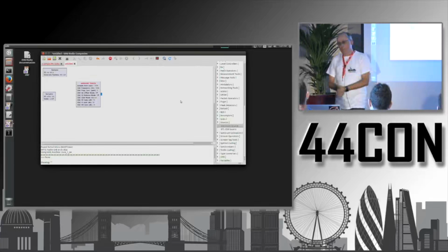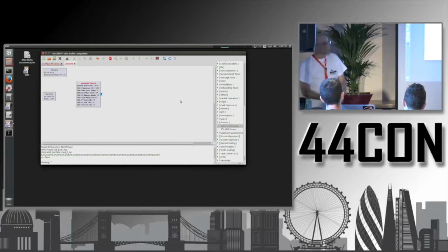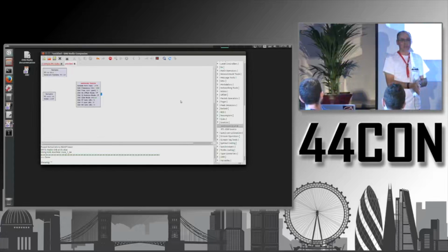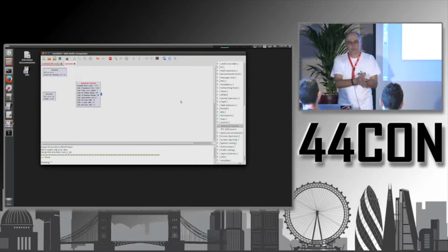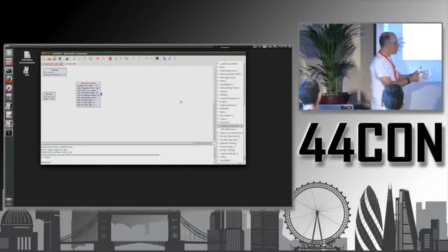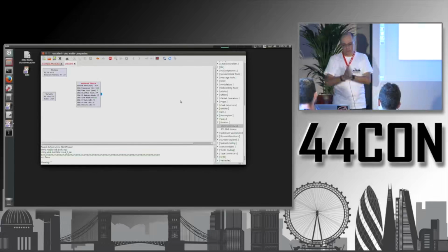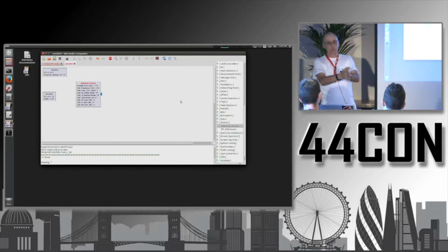With FM radio, we are talking about frequency modulation. And modulation is the following. Modulation means that you have your carrier signal, one frequency you are transmitting, for example 100 megahertz. If you did not do any modulation, simply put, that would be the pure frequency put out, precisely 100 megahertz and nothing else except for harmonics, but let's not talk about that. That's what you would get, just one thing.